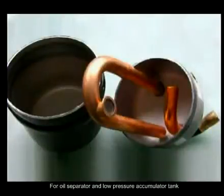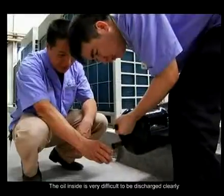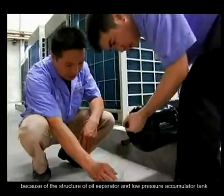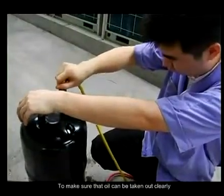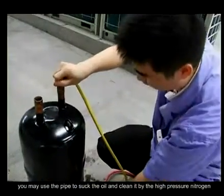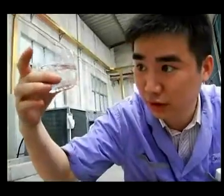For the oil separator and low pressure accumulator tank, the oil inside is very difficult to discharge completely because of their structure. To make sure the oil can be taken out completely, you may use a pipe to suck the oil out and clean it with high pressure nitrogen, or replace with a new tank.